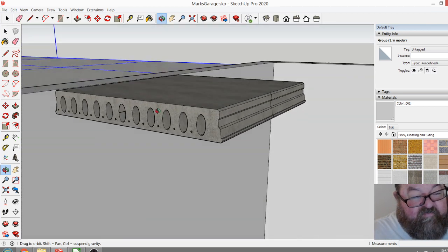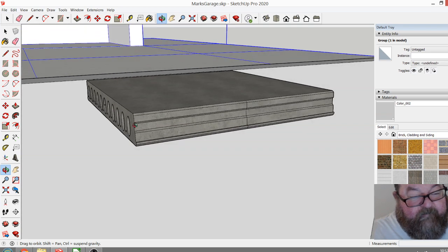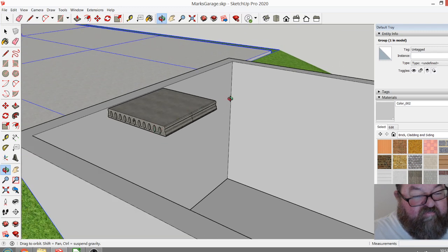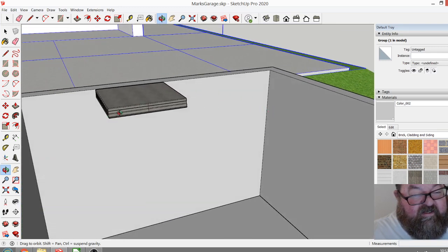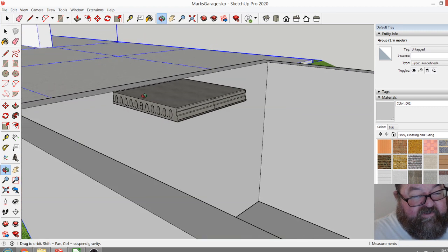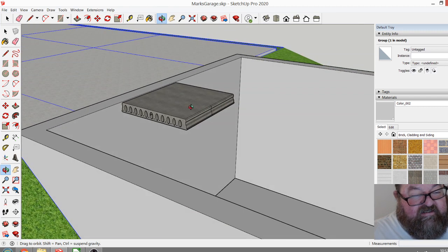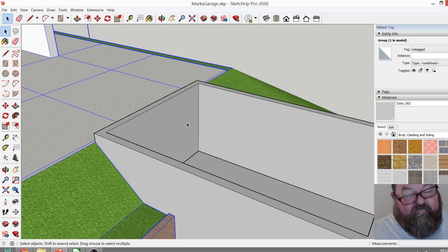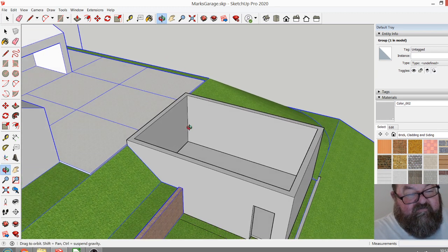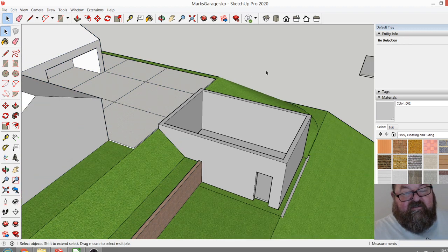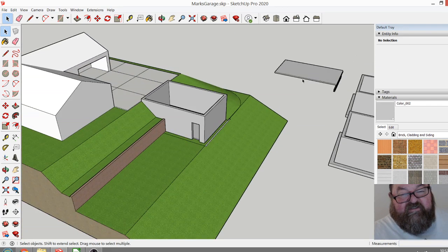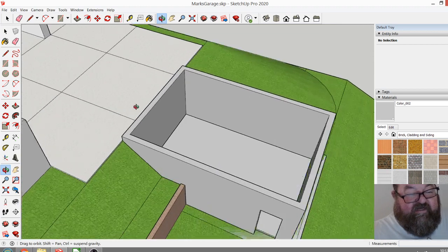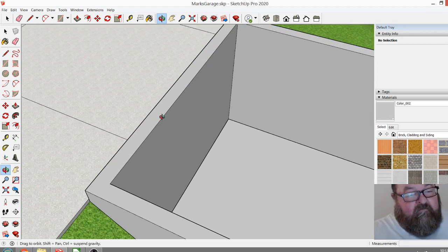It's basically a pre-stressed slab, and you can see the rebar in them. That rebar is pre-tensioned, and they have a camber in them. You can use them for parking garages and parking decks, and this is basically an elevated slab. But after doing that research and finding out the cost, I've decided to go back to this other system, which is basically a concrete pan and steel beams. But in any case, I would need a ledge here.